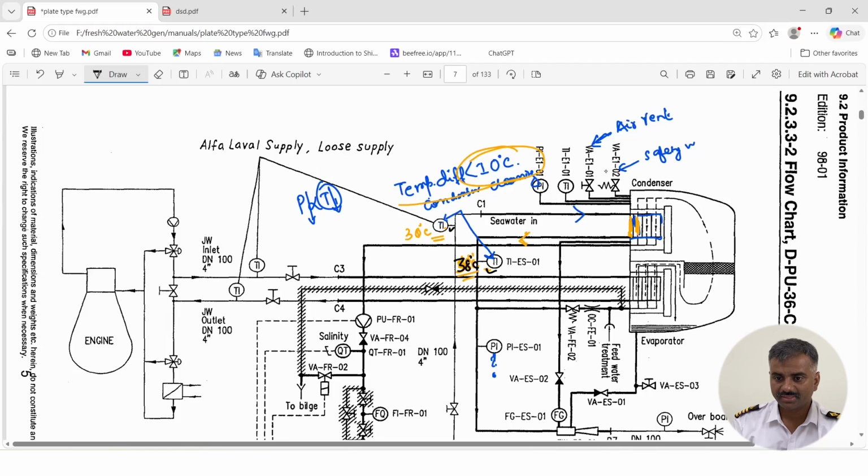You have got a safety valve over here to release the excessive pressure in the shell, because this is a closed chamber. You will always have an additional safety given in terms of a safety valve to release the excess pressure. Otherwise it is always in vacuum, but in case of an emergency, if freshwater or seawater is filled up and is not escaping from somewhere, the safety valve will generally lift.